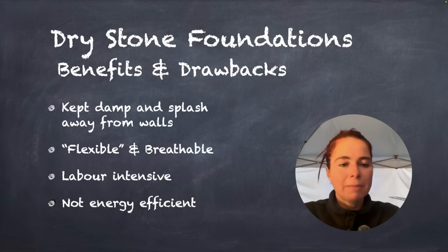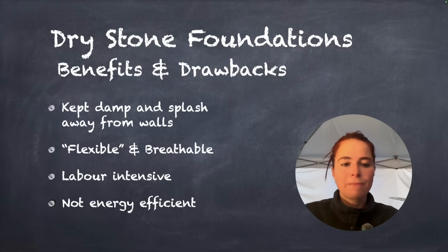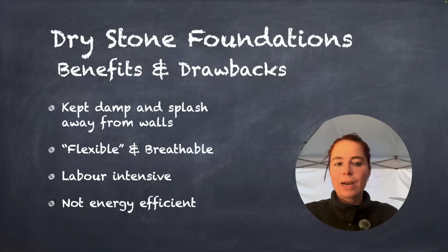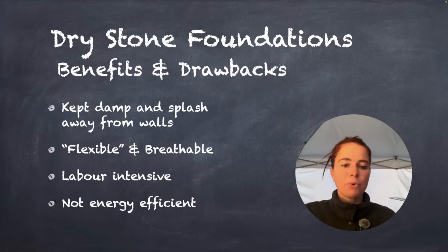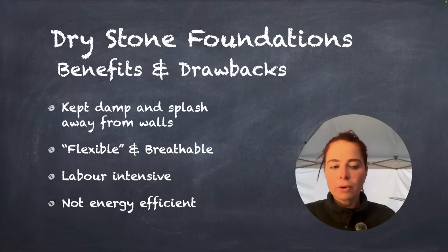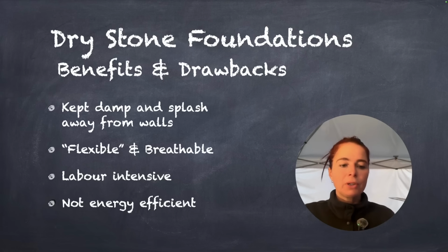So I'll talk a little bit about the benefits and drawbacks. I kind of alluded to these already, so I'll go through them quickly. It keeps the damp away from the walls above and avoids that splashback onto the more vulnerable walls above. Also, it's flexible and breathable, so it could move and adjust slightly, so it wouldn't be prone to cracking the way that concrete is. It's breathable, so moisture would evaporate quite easily.